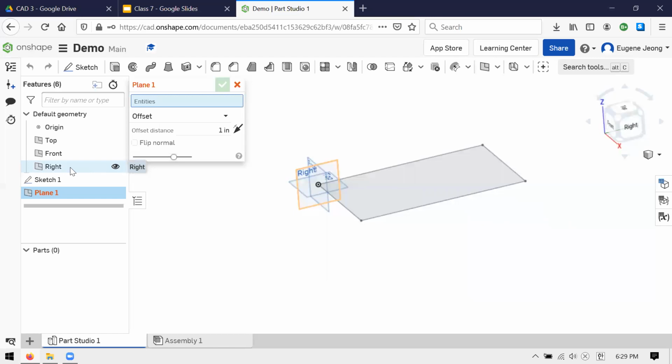You're never going to 3D print a right plane out of Onshape, and it's not part of the model. And yet you probably can't CAD if you didn't have these, because you need to define all of your sketches relative to some kind of reference. By default, you get the origin and these 3 orthogonal planes.